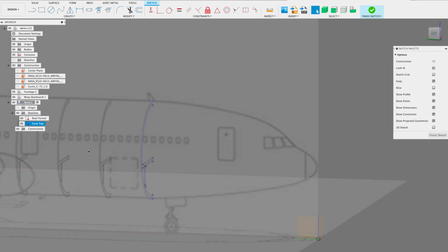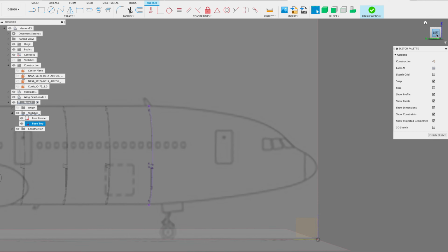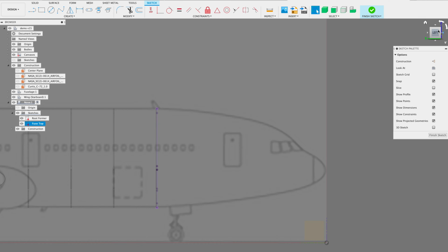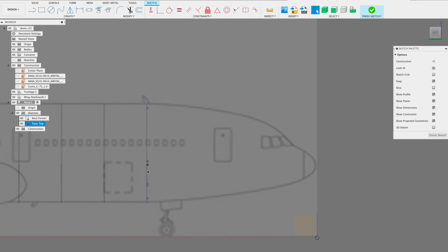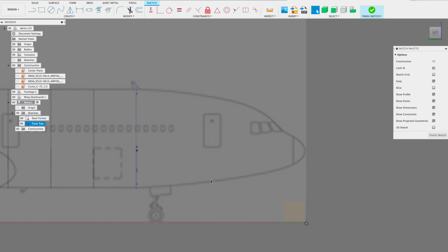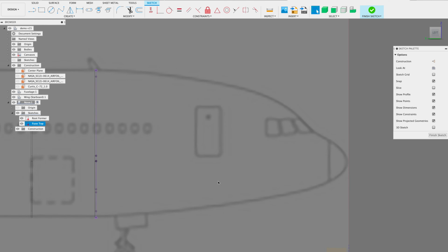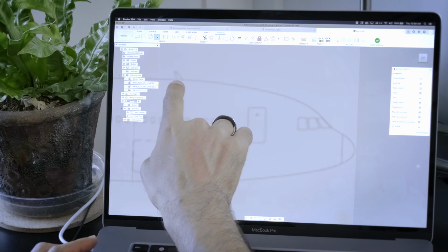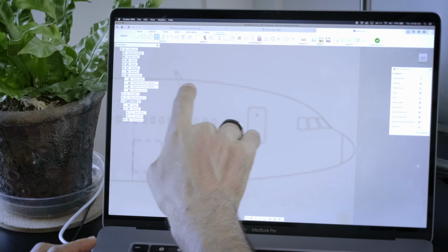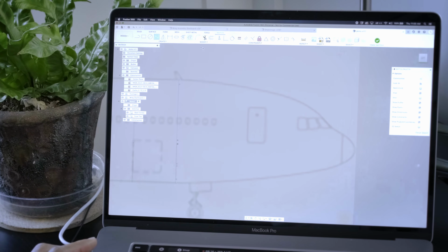Okay, and now let's go ahead and get a perfect side view by clicking on the left box here, so that way we're looking perfectly head-on at this. And what we're going to use is the fit point spline, and this tool is going to allow you to create a really nice curvature from here down to this point.